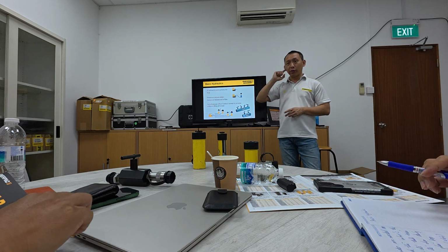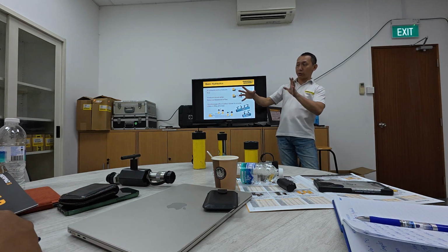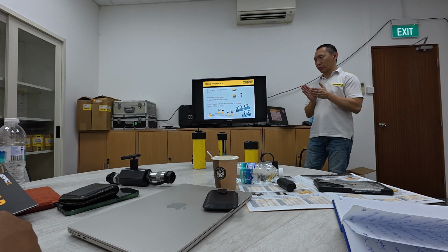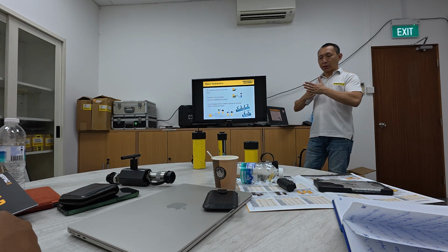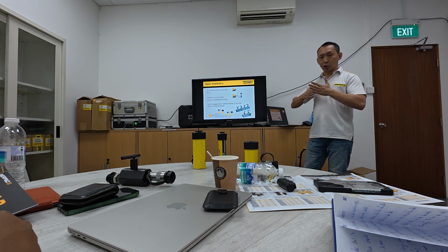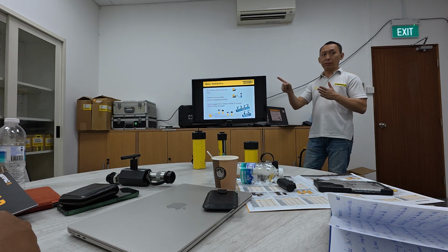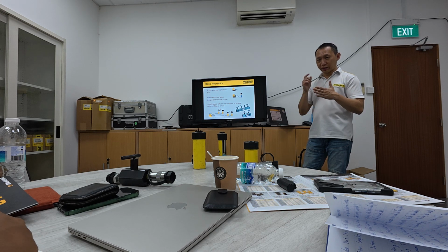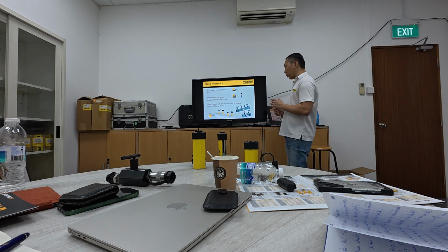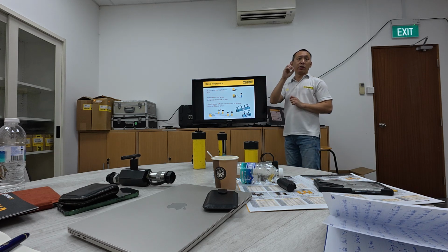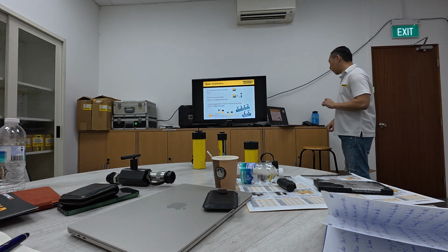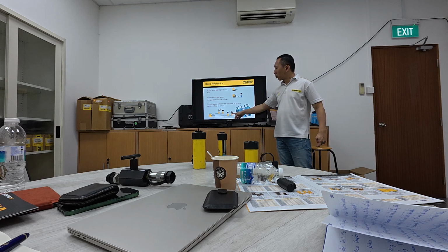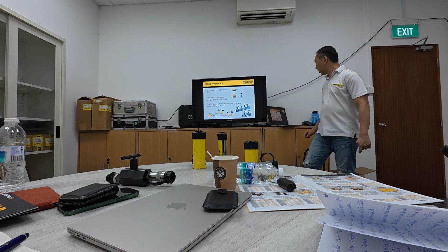A lot of customers think that when they turn on the pump, they expect full pressure. No, that doesn't happen. When there's resistance to flow, meaning something is resisting against the cylinder or the tool, then the pressure starts to build up, and after that it will move. So when there's no resistance to flow, it's zero pressure, or maybe very small pressure. The control valve helps to control the even lifting.